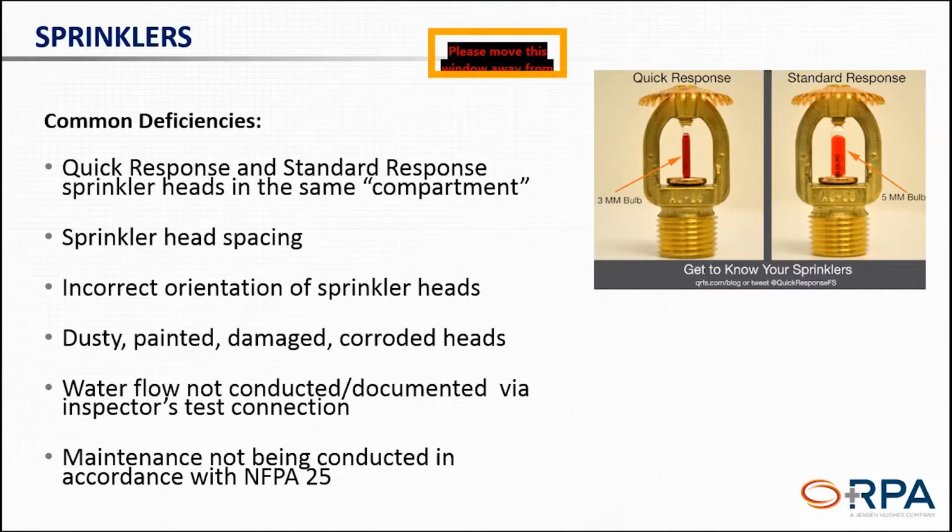Water flow was not conducted or documented via the inspector's test connection. We see that too, so just make sure your maintenance is being conducted in accordance with NFPA 25. Again, NFPA 25 changed in some fashions, not necessarily in frequency or anything, but definitely in organization of